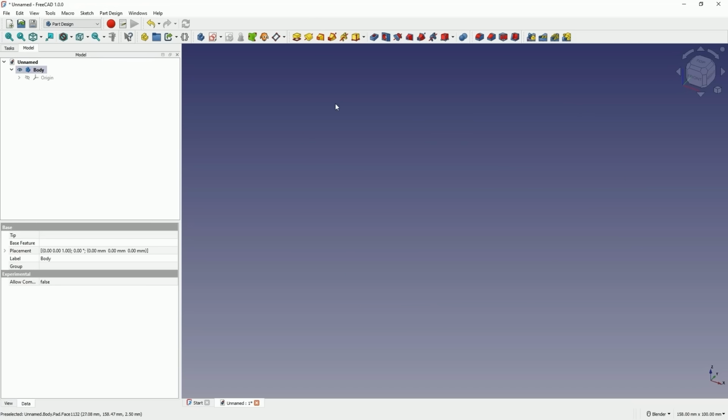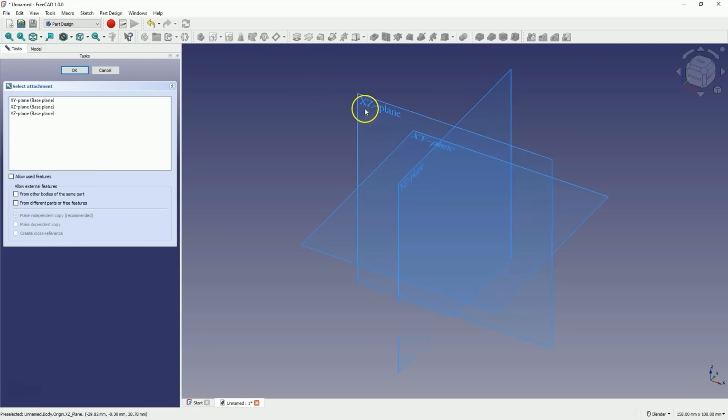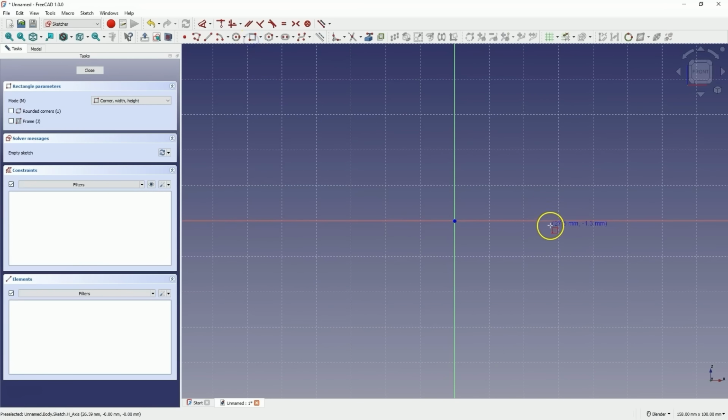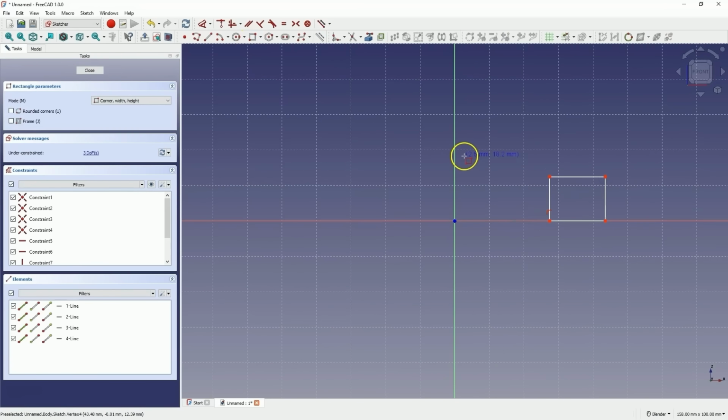The next fundamental operation for creating 3D solids based on a 2D sketch is the operation in which we create a solid by rotating the sketch around a specified axis. Here, to create such a solid, we need a cross-section sketch of that solid. Now, I will show you this with a simple example. Select Create Sketch and let's create a sketch on the XZ plane. Choose this plane and here I will draw a rectangle. Okay? For now, without dimensioning, I close the sketch.